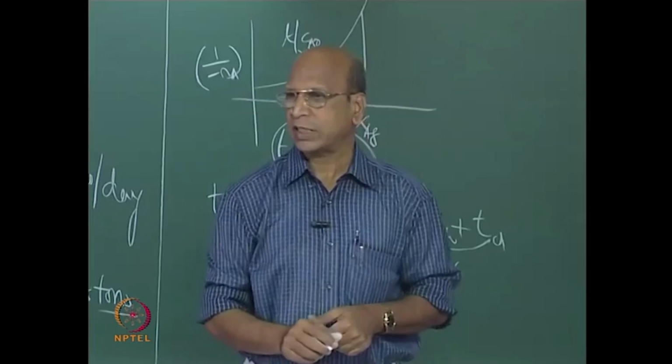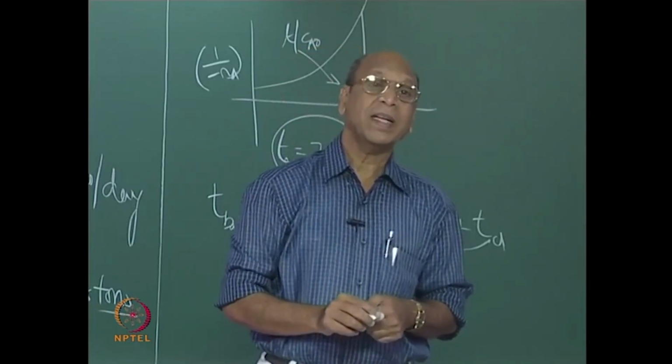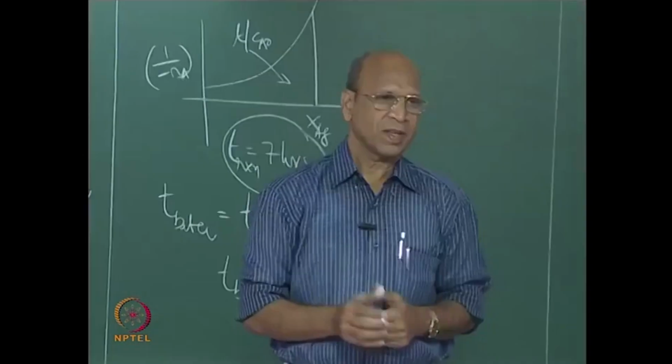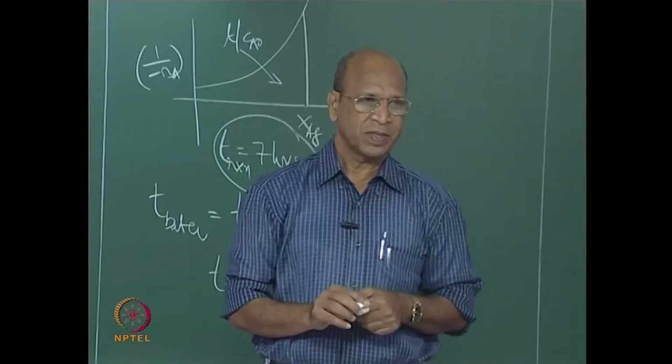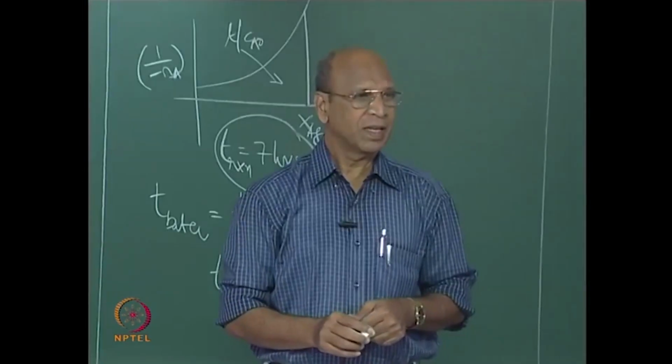Pooja says 1. We should choose such an L by D where the reactor surface area is minimum. You can never have that kind of thing, because for surface area per unit volume, only a sphere has the minimum. So our reactors are cylindrical. As the L by D ratio changes, non-ideality increases. What non-ideality? Dead zones. So what will happen? Conversion will be affected.